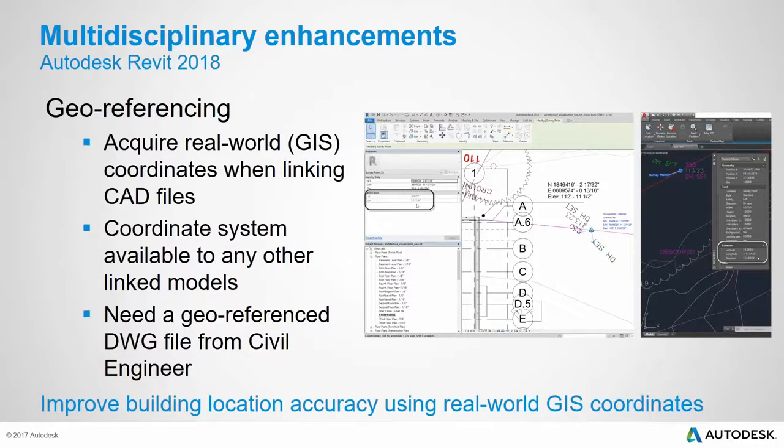So again, like I'd mentioned for the site files, I generally just center them on screen anyway because Revit's going to do it. And then once I get it positioned where I want, I pin it in place and then I don't ever move it. So yeah, you're still limited by that.